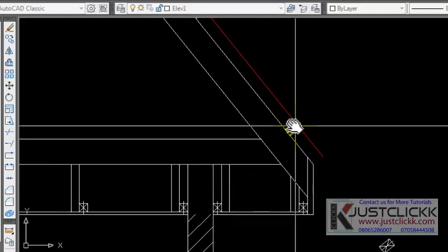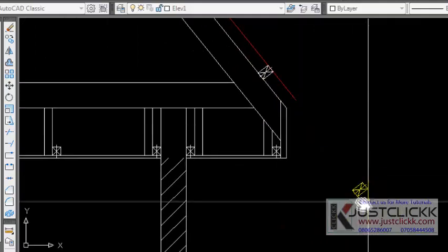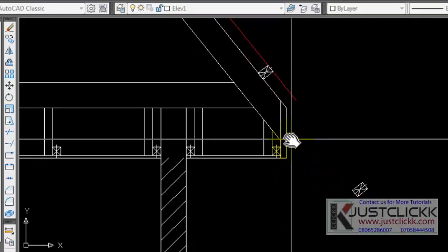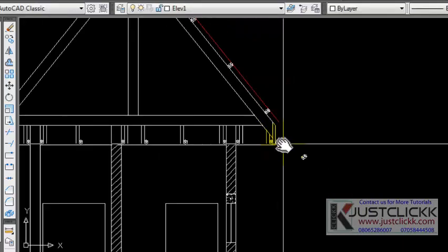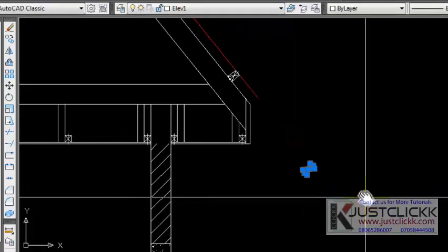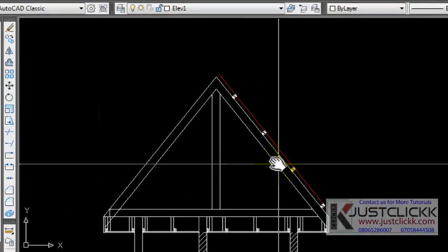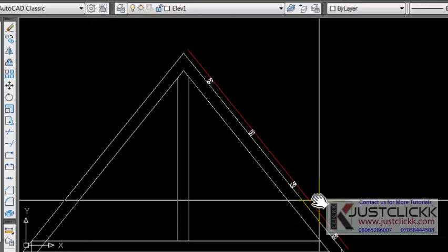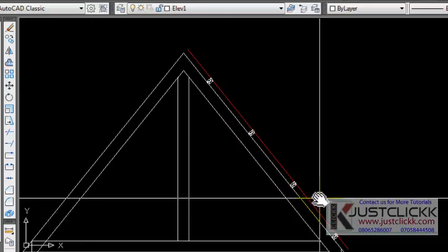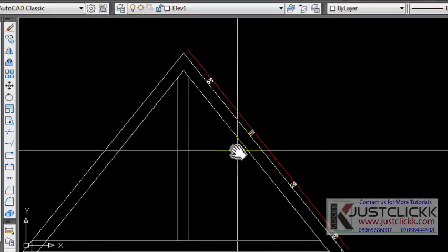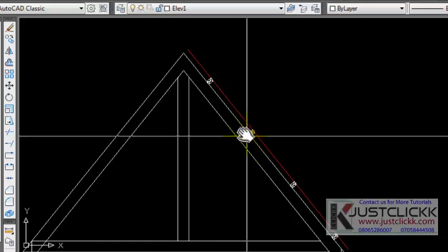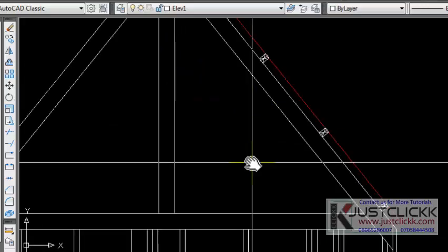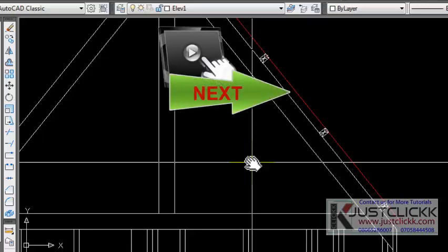Okay, I needed 4. One is overlapping, which I will definitely delete later. So press the enter key to accept it like so, and select this one and delete it. You just have to assume some certain number of polylines and give it to the array so that it will spread them. If it is in excess, you can always delete the rest. Now that we have achieved this, in the next tutorial we should be creating the trusses.